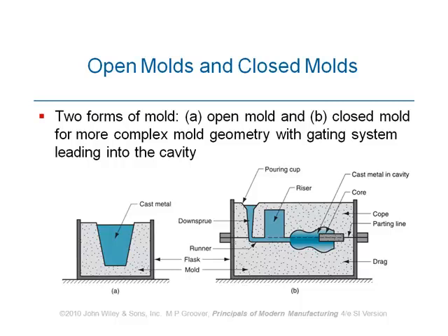Because inside is still in molten state, when it solidifies, it occupies less space. And as a consequence, some void spaces or cavities are produced inside the material, which is desirable or undesirable? It's undesirable. We have produced a part which looks okay. When you cut it, you see that there are some bubbles inside, which will affect the performance and functionality of the part after it is produced.